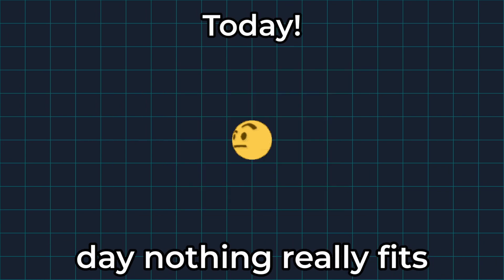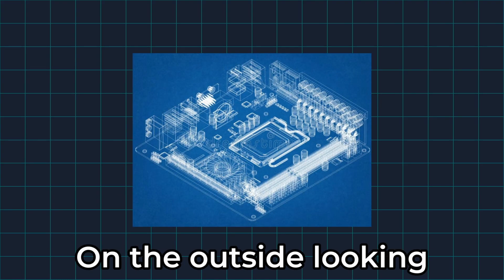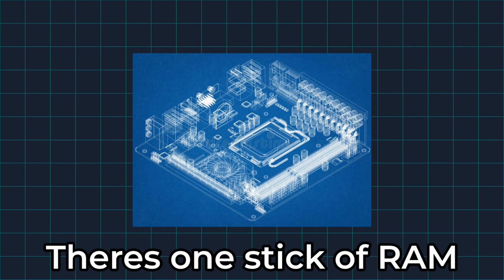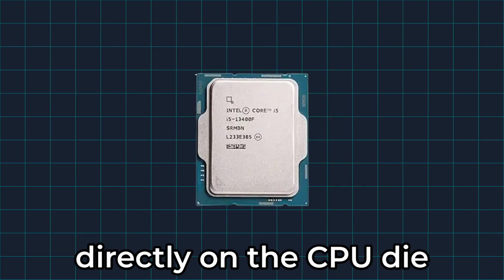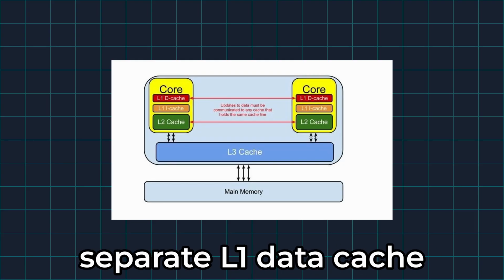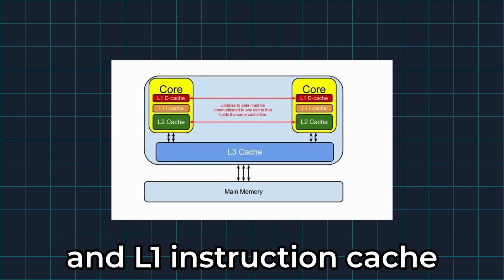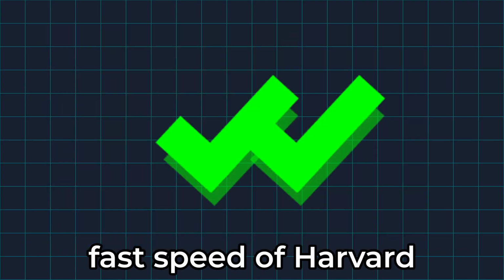Bringing us to the modern day, nothing really fits into pure von Neumann or Harvard. It's a mix of both of them. On the outside, looking at the motherboard, is von Neumann. There's one stick of RAM holding all your open programs. But on the inside, directly on the CPU die, is Harvard. The ultra-fast level 1 cache memory is split into separate L1 data cache and L1 instruction cache. You get the cheap simplicity of the von Neumann RAM, with the blazing fast speed of Harvard internally.